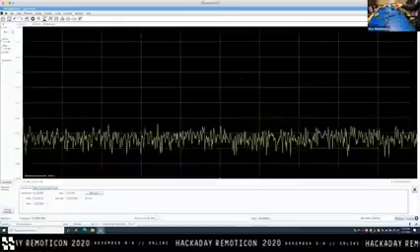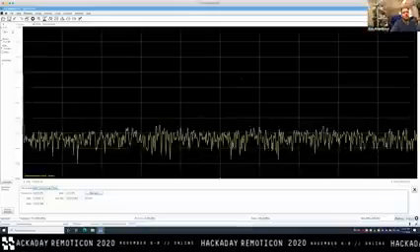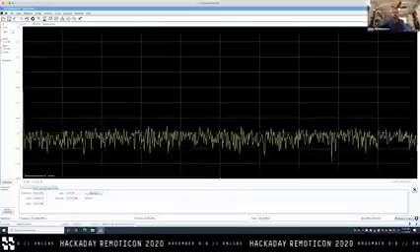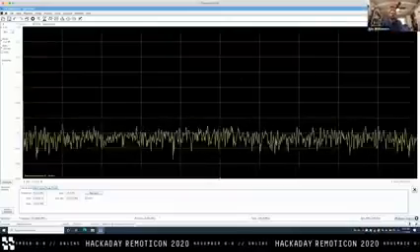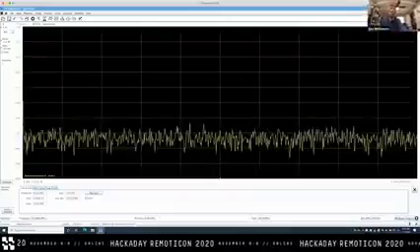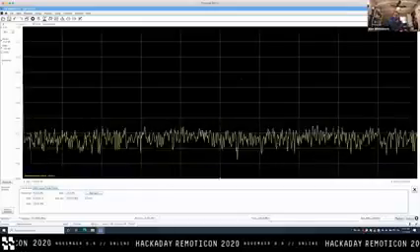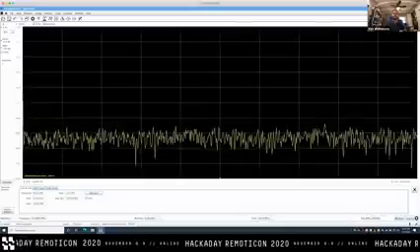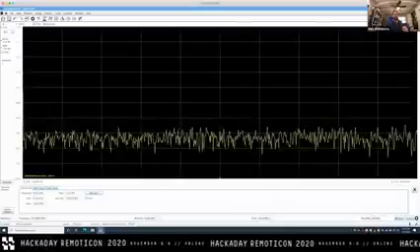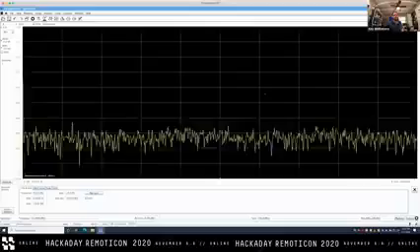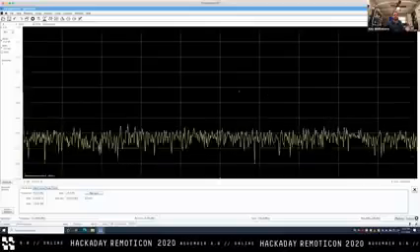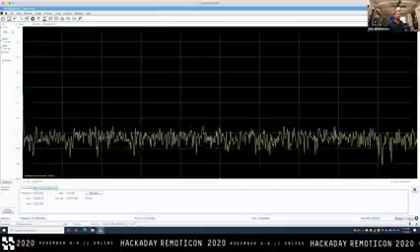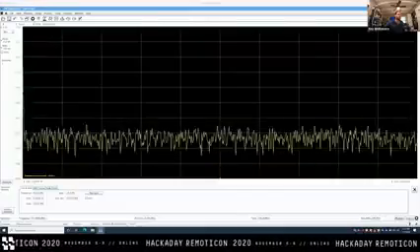So at this point, we have a halfway decent idea of what noise sources exist on our board and what's going on. And let's just assume that you were looking in this range because you had a 60 megahertz failure in your test report or something like that. Although you can just hunt arbitrary signals this way. It's just if you don't know that they're failing yet, then it might not be worth your effort to try to correct them. But sure enough, we've got those loud signals.